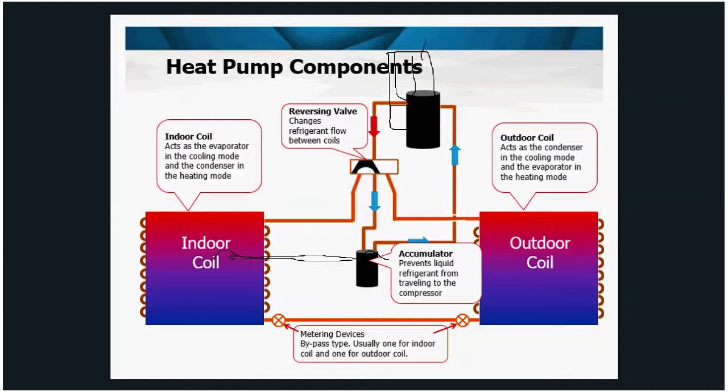So refrigerant will dump into this accumulator, and it will be allowed to boil off. And as that refrigerant boils off, it enters the outlet tube here, which is shaped like a U, and then goes back to the compressor. At the bottom of this little U-shaped tube is an oil pickup. It's just a very, very small port, and it's there so that any oil traveling through the system will be allowed to go back into the return side, going to the compressor, and return that oil back to the compressor. Again, you have to imagine that it's just this deep, and disregard this other piece down here.